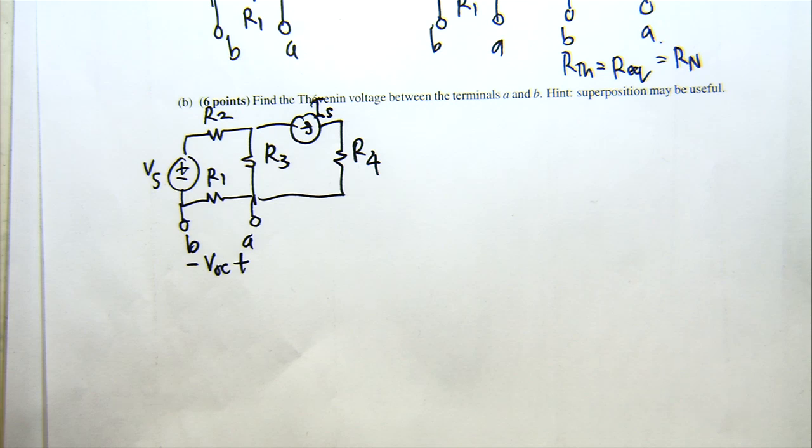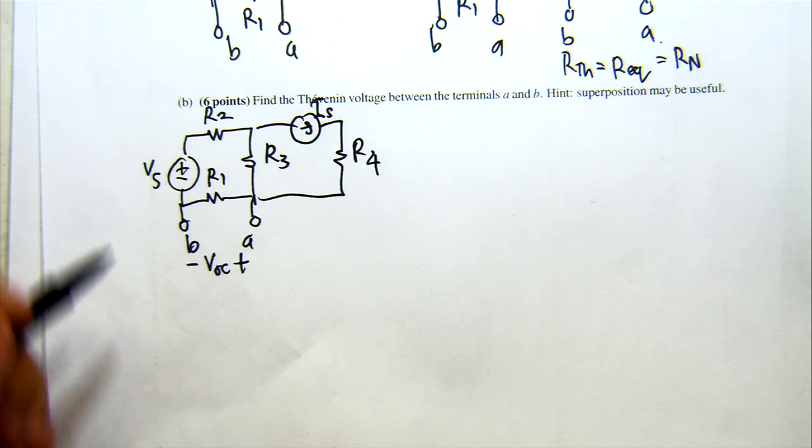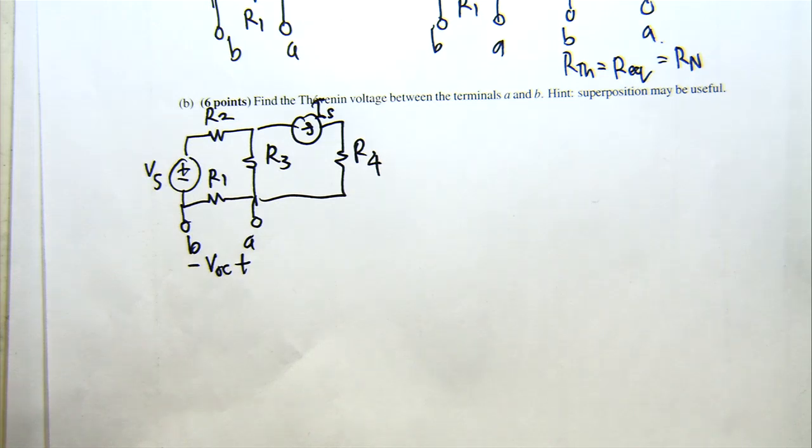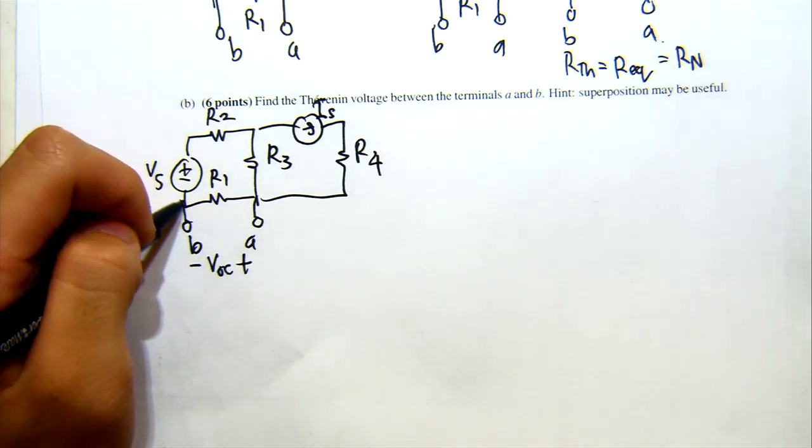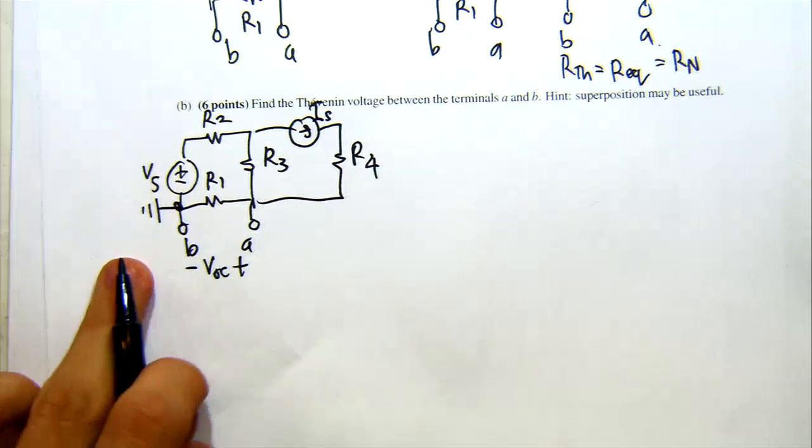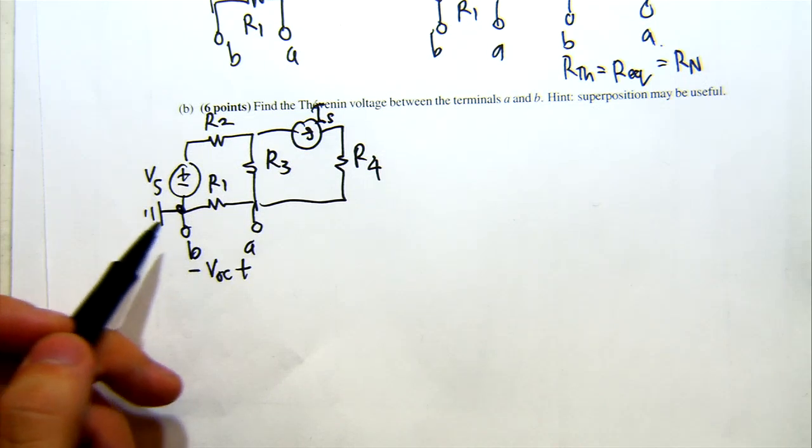One thing I'm going to do in particular to help aid analysis is I'm going to choose a node as ground. If you choose a node as ground, then this can help us do node voltage analysis because it gives us a reference, someplace that we're saying is 0 volts. So I'll choose right there. You'll see why in a little bit why I'm choosing this node.